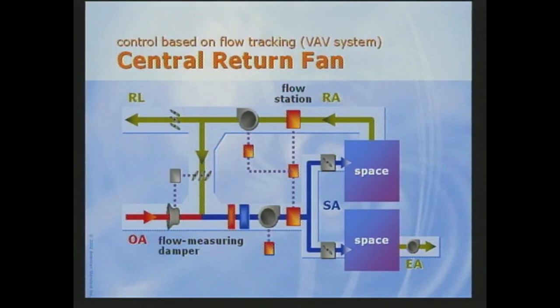An airflow sensing station determines supply airflow. A controller subtracts a fixed value to compensate for local exhaust and exfiltration to find the return airflow set point. The controller senses return airflow and modulates return fan speed to maintain the calculated set point. Building pressure is indirectly controlled provided the airflows are sensed accurately.